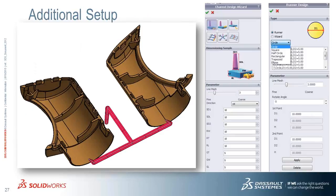There are some inbuilt layouts for designing the sprue and runner or gate layouts, which helps the user to basically speed up the process. The user actually just has to create a sketch that represents this layout and can define that sketch as a gate or a sprue or a combination of both.